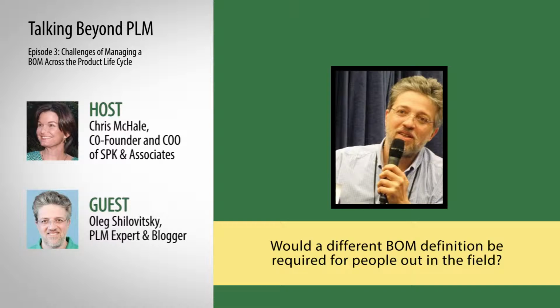Yeah, that's another great question, because it depends on the industry, it depends on the product. You might see different bills of material outside. Let me give you a simple example. For a product that is manufactured with a particular serial number, you will have to keep what's called a serial number BOM for a particular instance of the product.